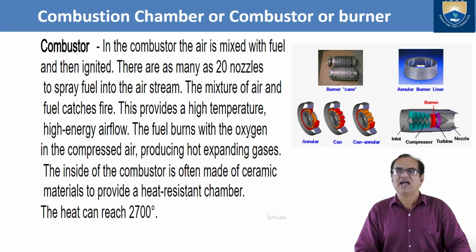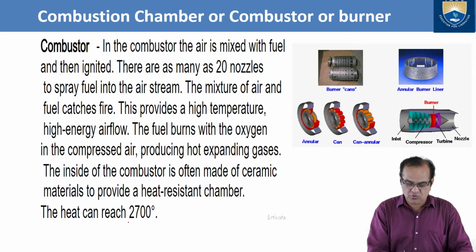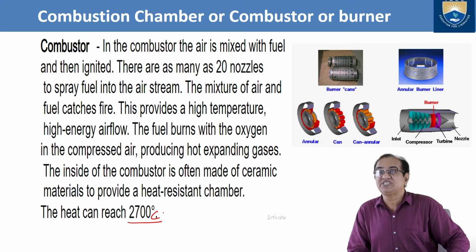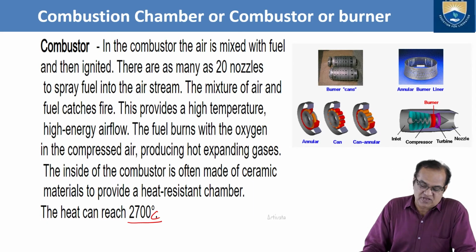This provides a high temperature, high energy airflow. The fuel burns with the oxygen in the compressed air, producing hot expanding gases. The inside of the combustor is often made of ceramic materials to provide a heat resistant chamber. The heat can reach up to 2700 degrees centigrade. This much heat can be obtained.